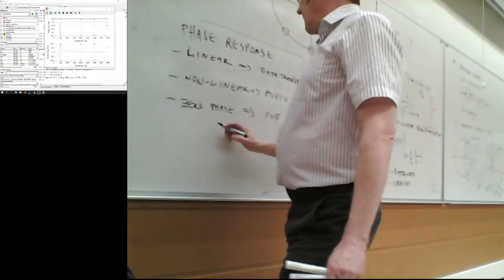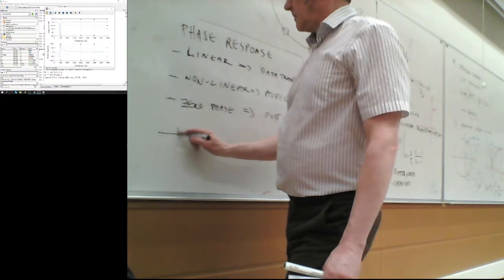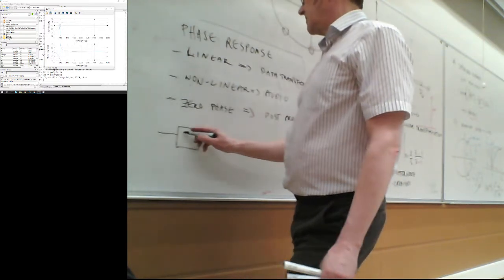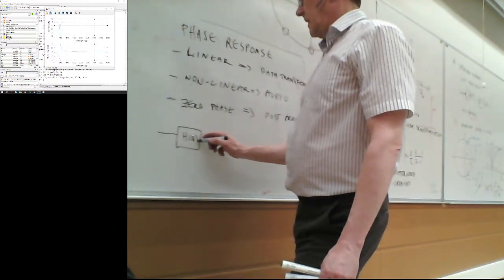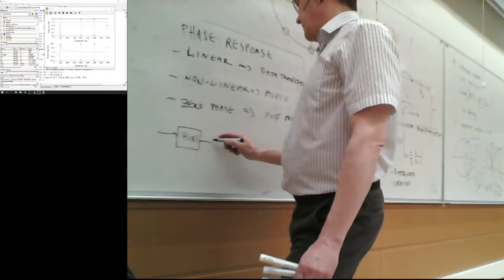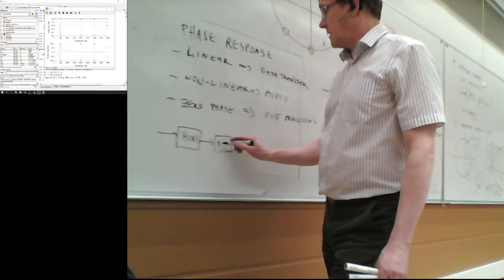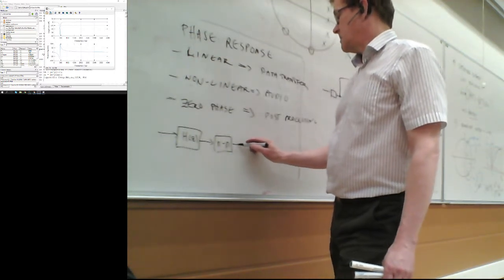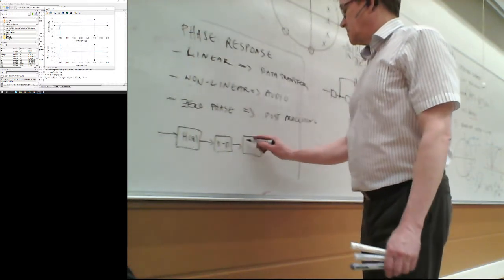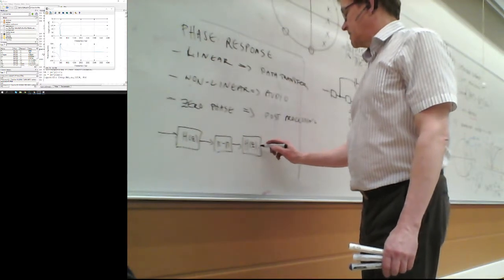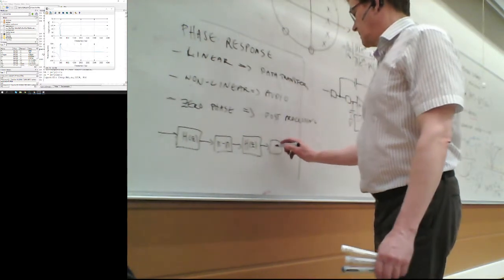But in reality, those digital filters are, generally speaking, real-time filters. Anyways, zero phase means that if you first put the system through the H of Z, then reverse the time, put it again through the same system, then reverse the time again.